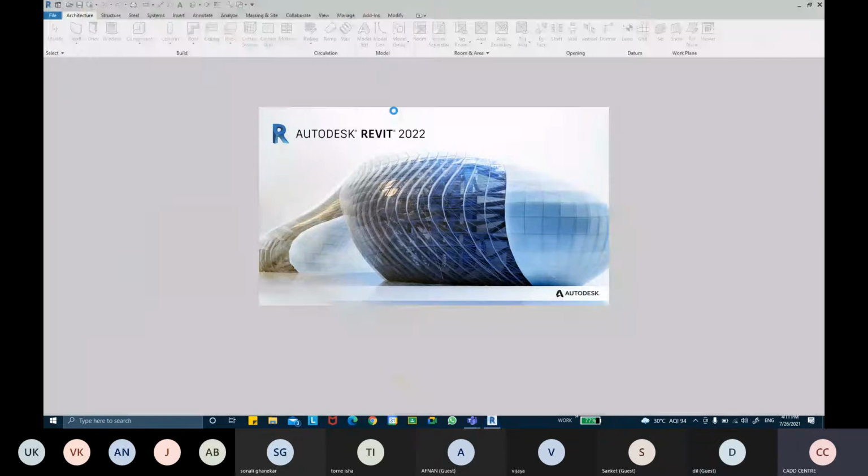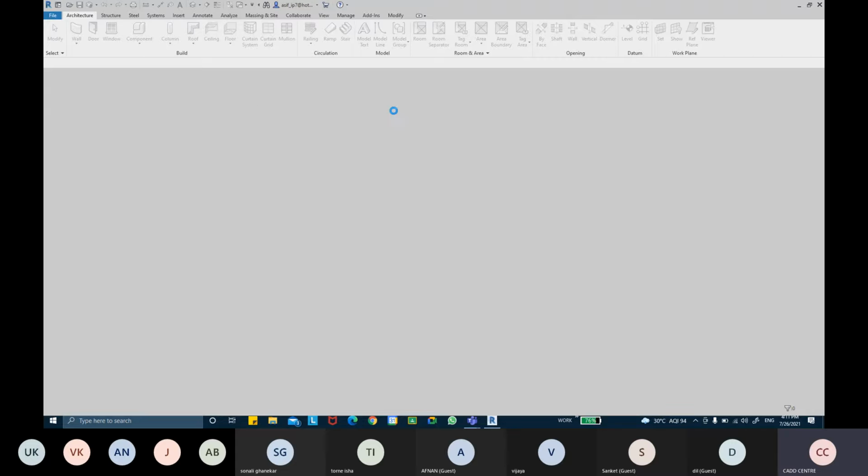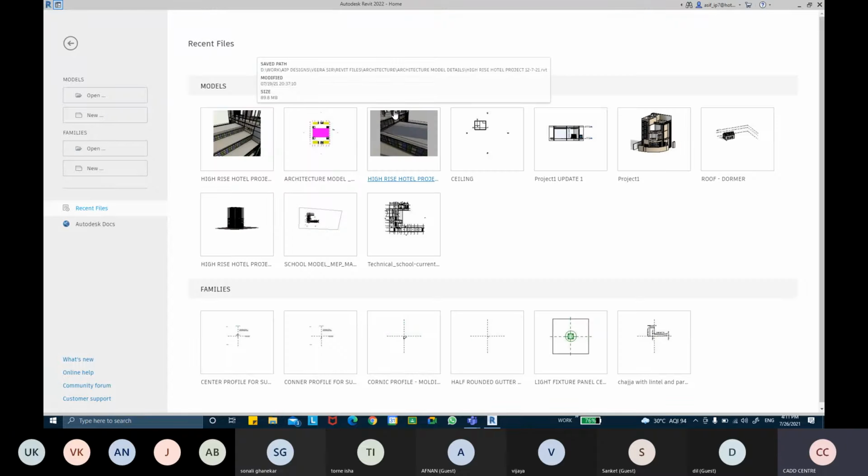So in the previous class we did the topo surface, and we created some topo surfaces. We saw the building pad, split surface, merge surface, and sub-region surfaces, and we did the contour markings. Today we were left with one thing in the topo surface, that is the site, the graded regions. We'll see how the graded region actually works.